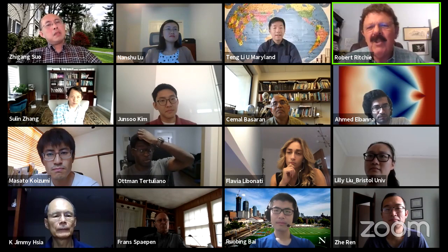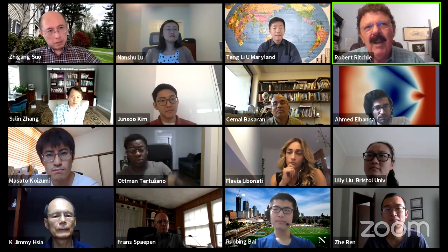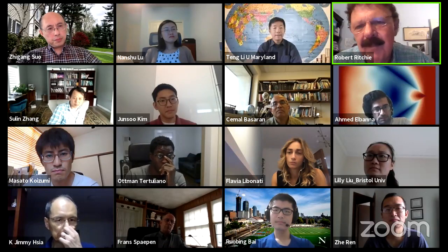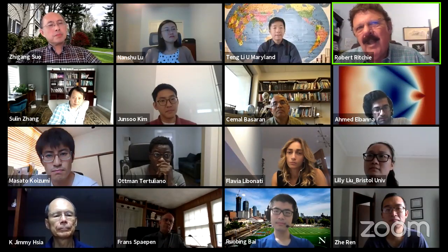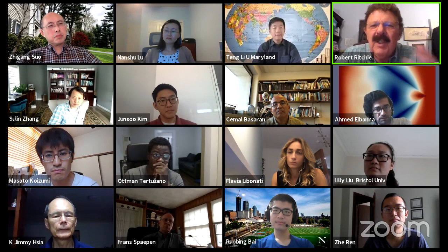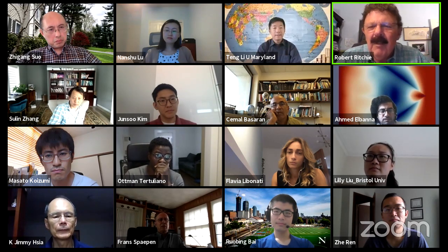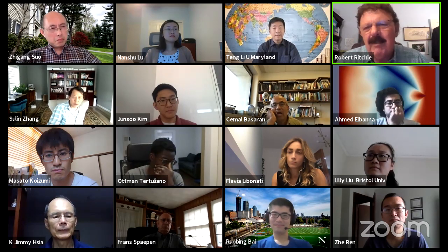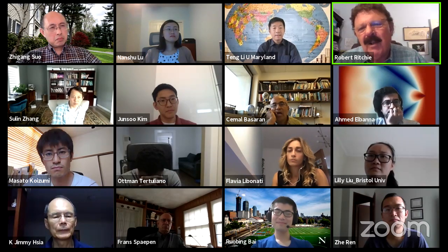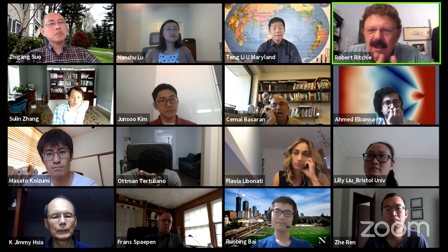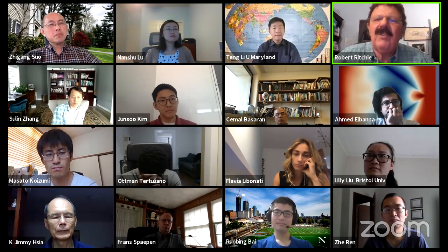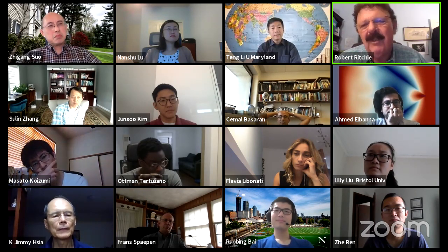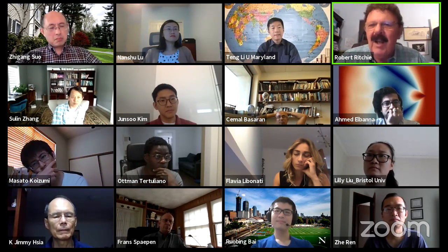And that's why I tried to push this concept, because, for example, if you refine the grain size for fatigue, that is good for fatigue strength generally, but it's terrible for crack growth when you've got an extrinsic effect, because you've got roughness induced crack closure. So the irony is you get completely different effects. If you change the yield strength, it will affect the intrinsic versus extrinsic mechanisms in a different fashion. So therein lies the rub.